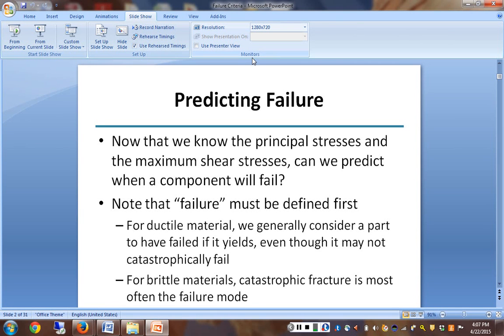And failure criteria sounds like, okay, did it fall down? If you remember back to part 2, when we talked about that bearing failure, that's an engineering failure, but it is not necessarily a structural failure. So the engineering definition of failure includes the fact that it deals with its yield strength. It doesn't necessarily deal with something falling down or something breaking.